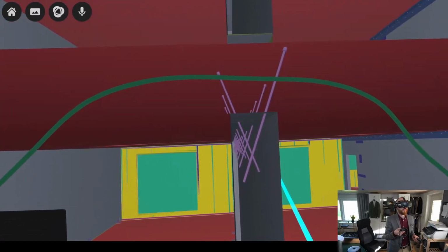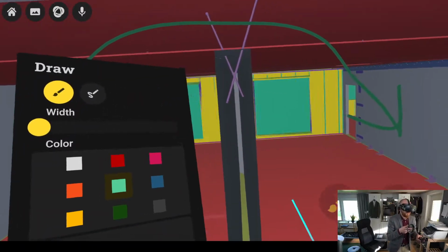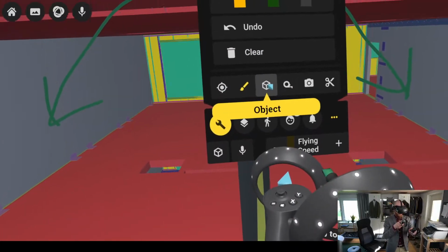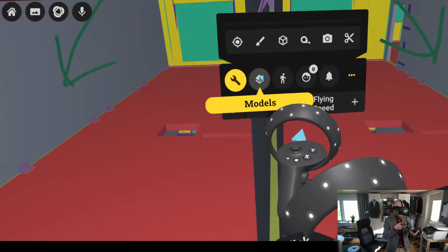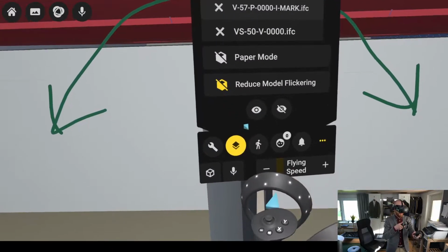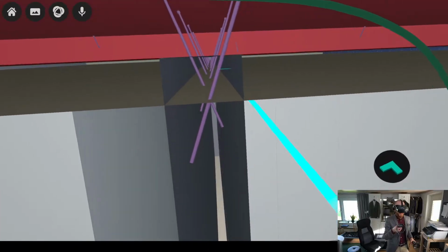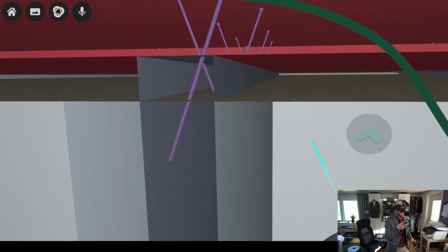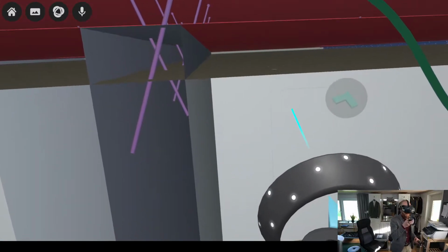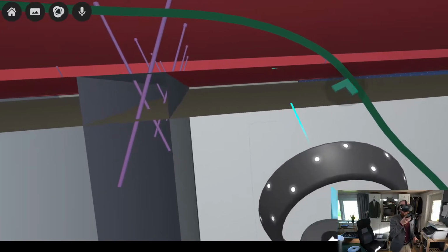So how do you solve this then? Now what you do here is that you have to install a suspended ceiling. Let's take a look at the architectural model here. So in this case, we've added a suspended ceiling. Now we can't see the exact details in this model, but it's one layer of gypsum, and then there's some wooden laths here.